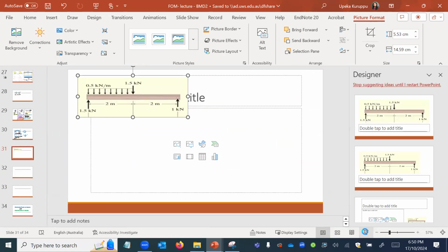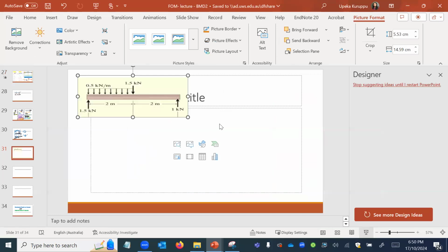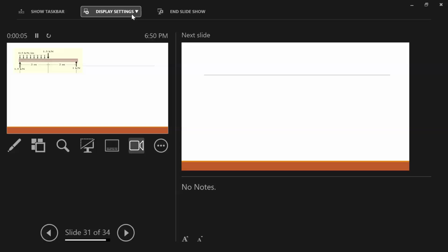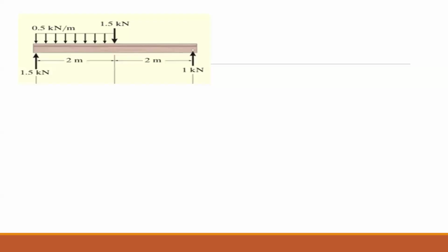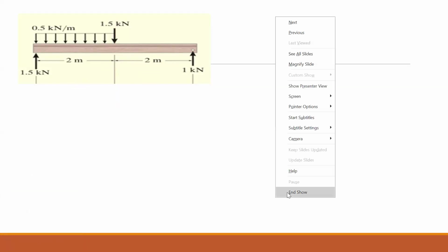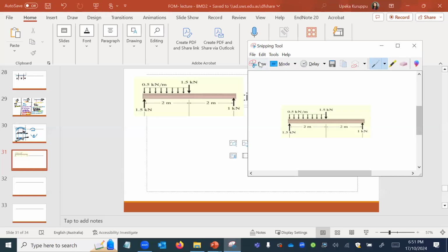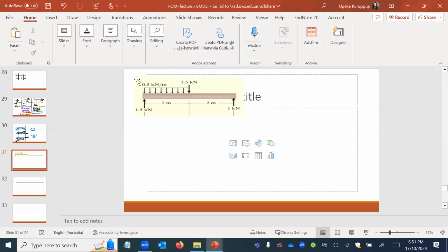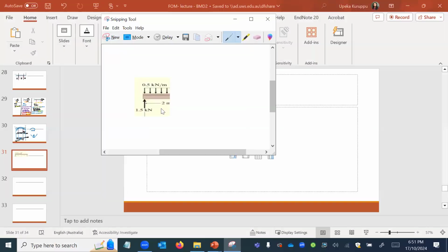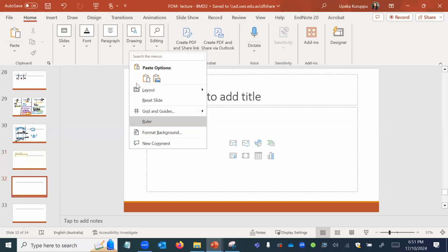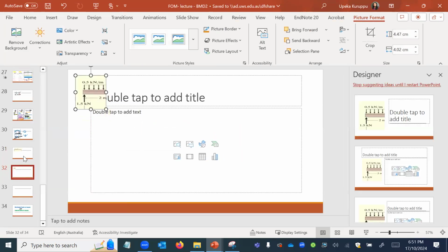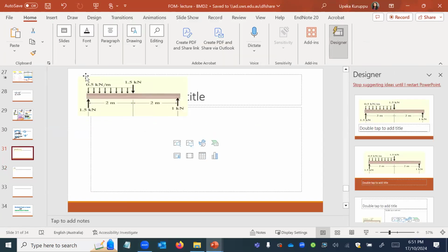This is the hardest that we can give you. I told you, you only have uniformly distributed loads, and actually in the universities, those students have other different types of distributed loads as well. But in our case, this is more than enough. So if you get a question like this, let's see how to do this. Here again, you need to section at two places, two sections. So I need two parts. One part will be like this, and the other part will be like this.